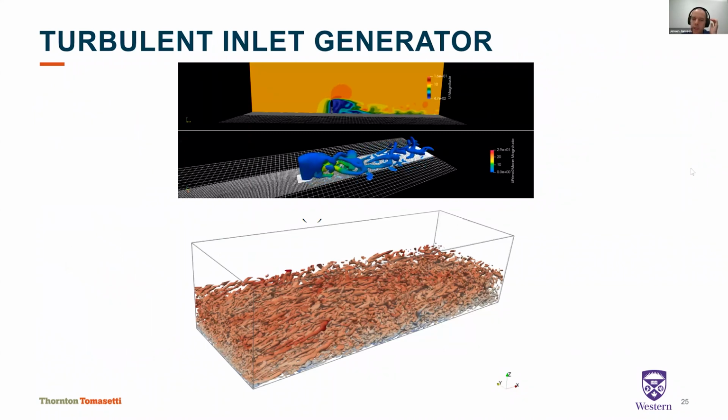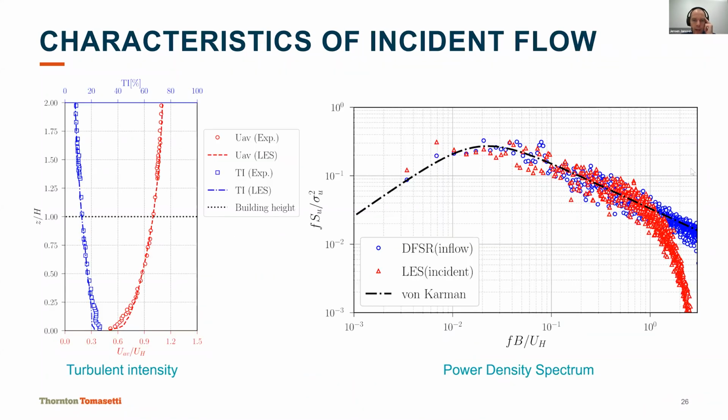So we're really focusing on those first 3 boxes, and they developed this turbulent inlet generator specifically for OpenFOAM. And it's matching brilliantly. So it's not only the easy part, relatively easy, matching the mean flow characteristics of air flowing over urban terrain. They've also looked at the turbulent effects and basically the statistical dynamic effects of the wind to match that.